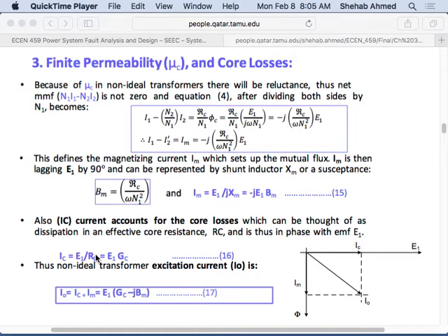There is no resistance in there, right? We found that there's an additional amount of current being drawn, and this amount of current is actually in phase with the voltage. And we said, okay, if it's current in phase with the voltage, and it's due to the fact that I will have a voltage generated, it's required for me to generate that voltage, then I will call it the core loss component. So it's representing everything due to the hysteresis and eddy current, or the real power losses in the transformer, not the reactive component, the reactive power that's available in the transformer.